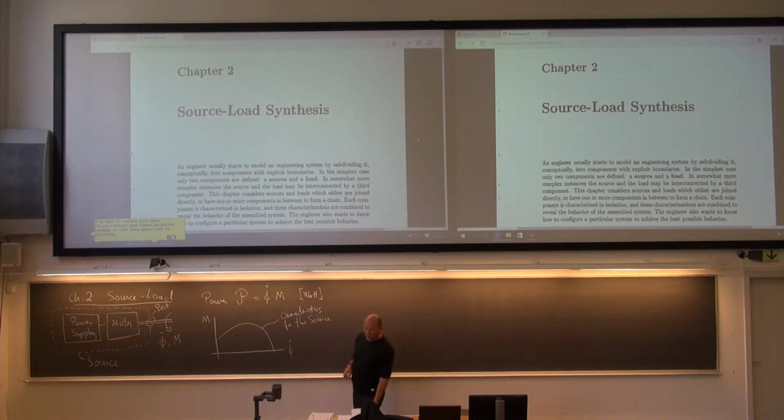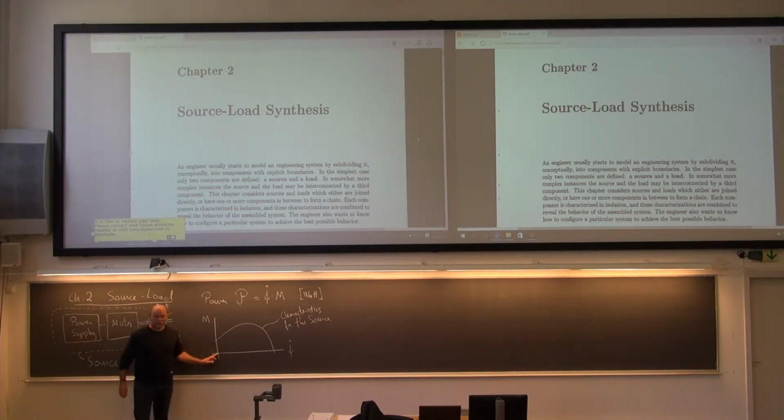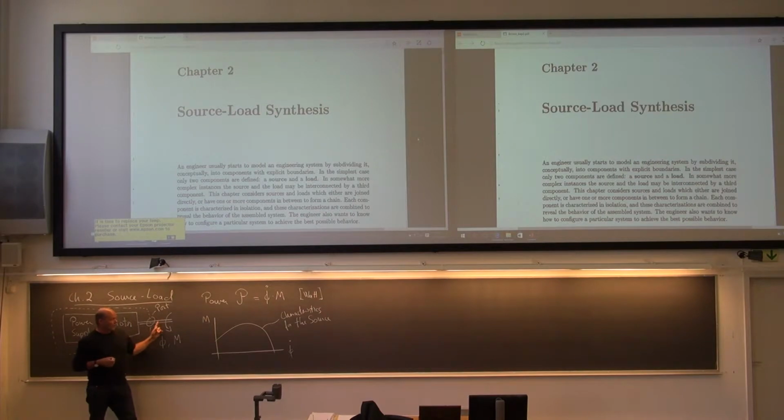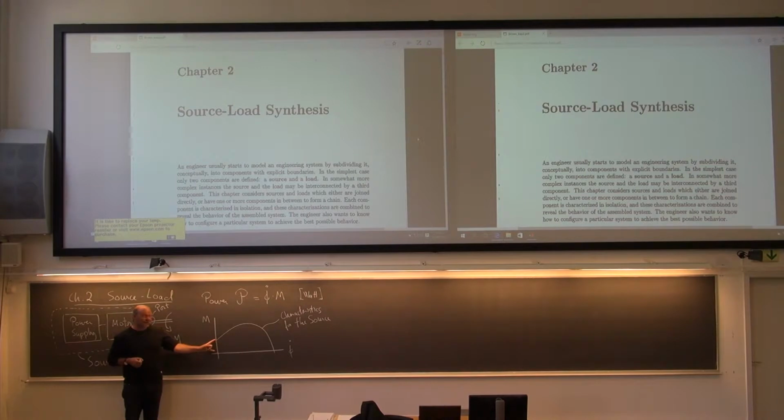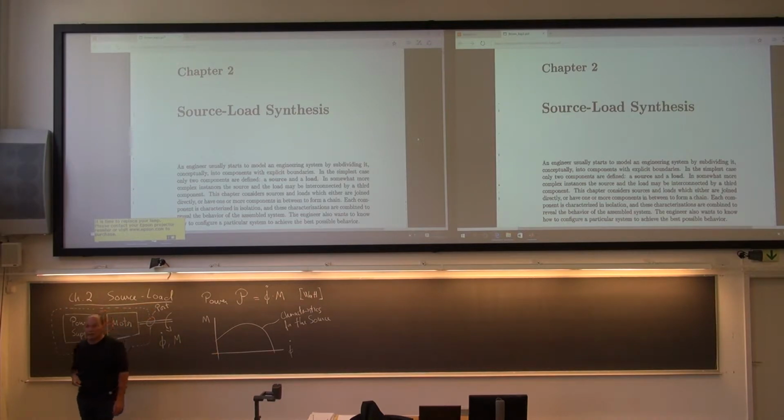So then you can see when you switch this power supply on, it is going to start to rotate. Initially the speed is 0, it doesn't rotate at all. Then you have this much torque on this axis. And on some motors you will find that it is extremely weak in the beginning, so this one may be even close to 0, meaning it can be very hard to get things started.